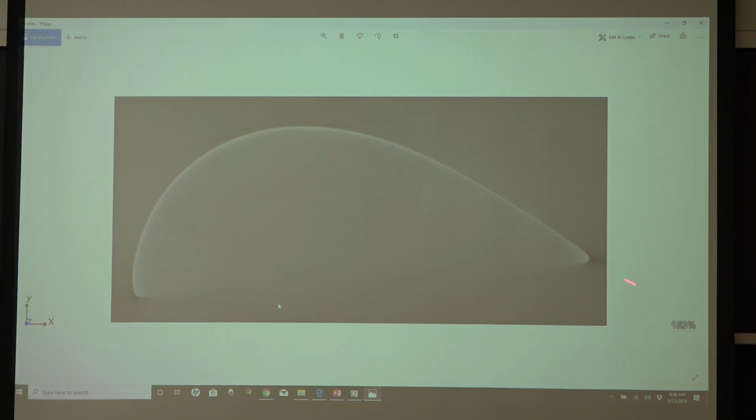And for this sample, it's dependent upon the internal cooling channels, so it's the scattering of the X-rays through the sample. In the open void space, there's nothing in the X-ray's path, but when it hits the inner wall and outer wall, there's other scattering. So this is what happens if you don't fully penetrate the sample at the appropriate X-ray level.